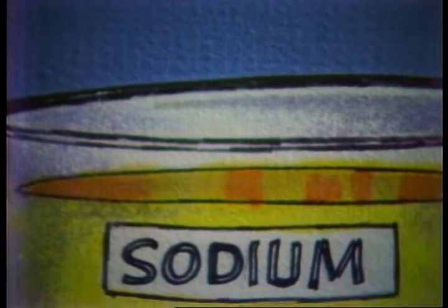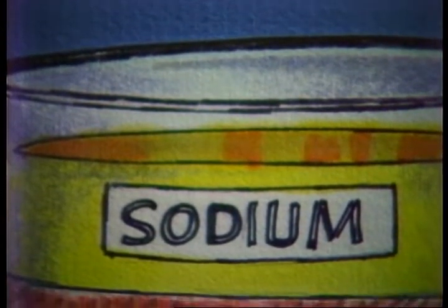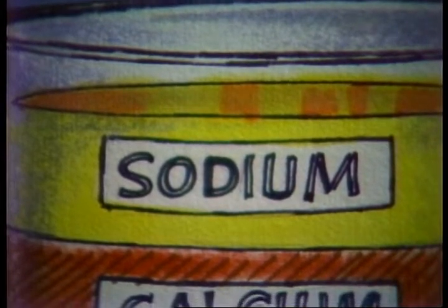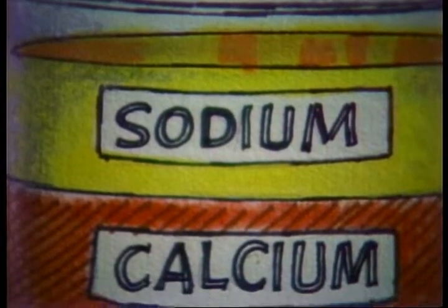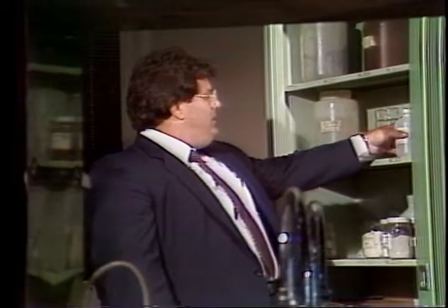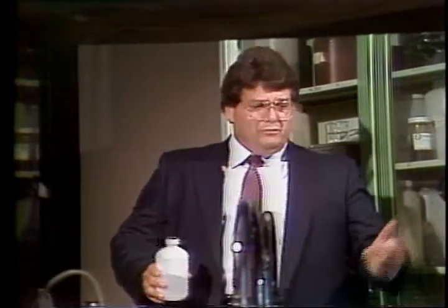When we talk about these salts, we can be talking about anything from calcium salts to regular sodium chloride, table salt. When bentonite and salt minerals mix, a chemical reaction takes place. Bentonite and salt just don't mix. As a matter of fact, when they do mix, we have some strange things occur and we lose two of the properties that we discussed earlier. The first being we lose control of viscosity. The second, we lose fluid loss control.